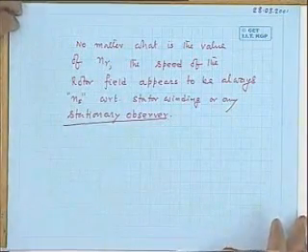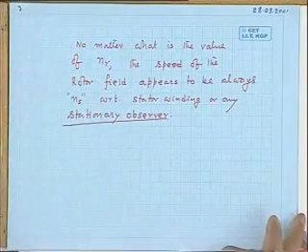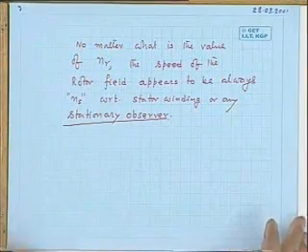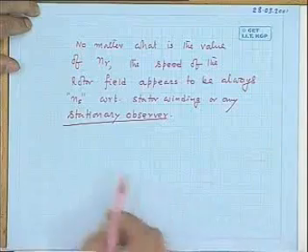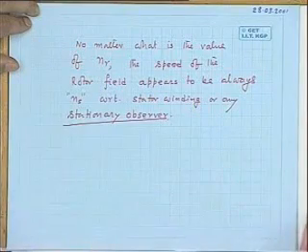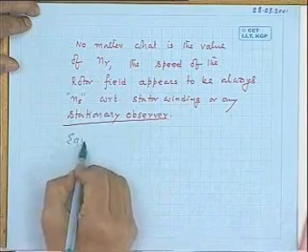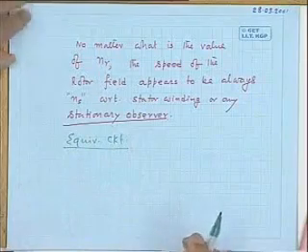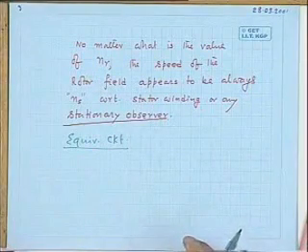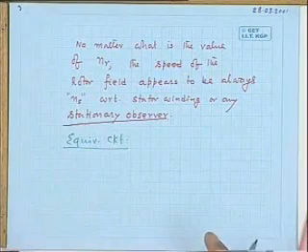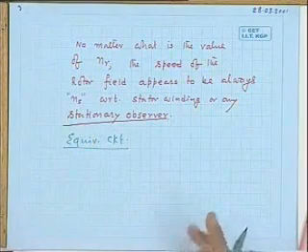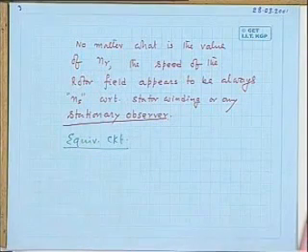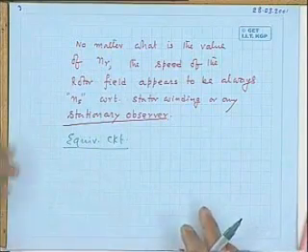Okay, now we were discussing the equivalent circuit, how to draw it. The equivalent circuit of an induction motor can be developed along the same lines as that of a transformer, because there is a primary winding and the secondary winding is loaded. Loaded means here it is shorted. So it is an extreme kind of loading you can think of.